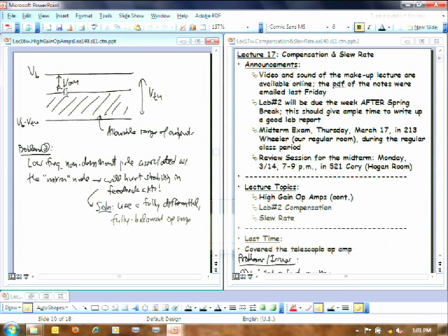That's a big problem, right? Because we talked about why output swing was so important. Output swing determines how large your signal-to-noise ratio can eventually get, which is a definition of dynamic range in the end. You want to have the largest output swing because you divide that by the minimum voltage you can accept, which is determined by noise. That gives you your dynamic range. Dynamic range is an important parameter. If we don't have enough output swing, we can't get good dynamic range.